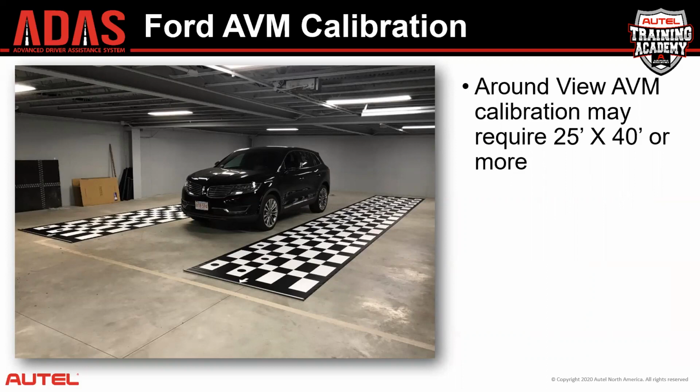Now, most calibrations, especially camera calibrations, need to be performed indoors in a controlled environment. However, Ford specifically states that it is possible to perform this particular calibration outdoors, as long as the ground is relatively flat and level, and you're not calibrating in direct sunlight that would wash out the black in the target, where the camera couldn't recognize the contrast between the black and white. There's always ways around these bay space requirements if you get creative.